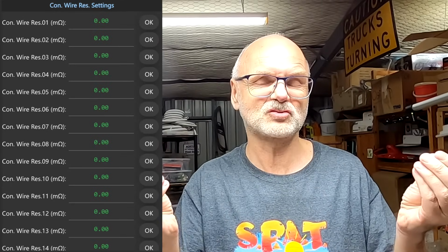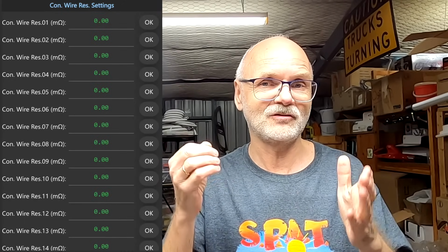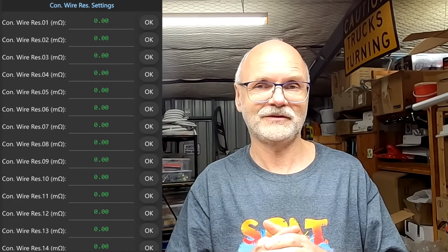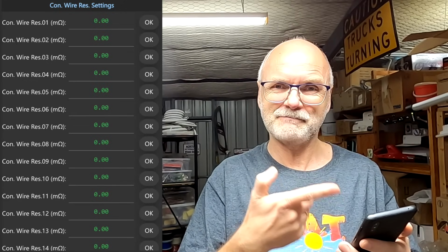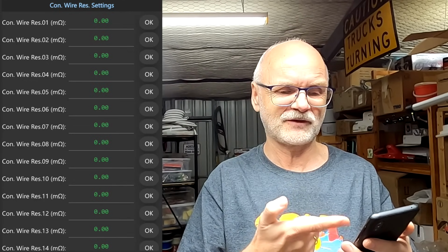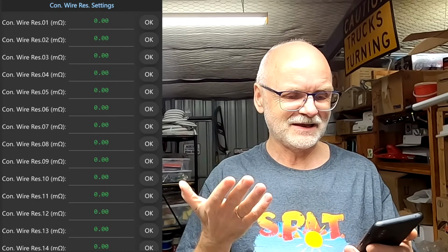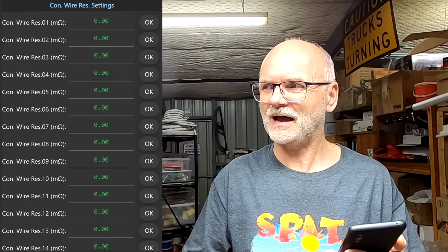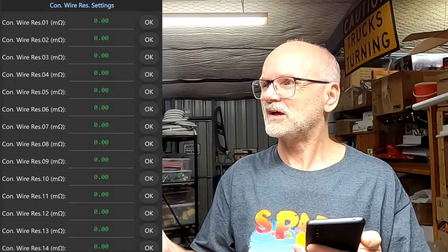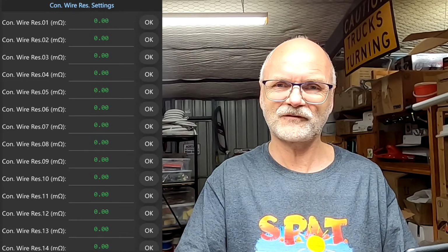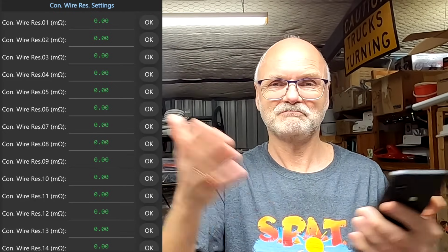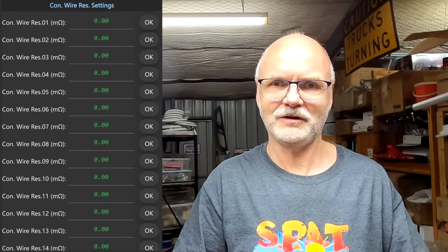There will be a voltage drop on these tiny cables, especially here with the JK-BMS, and you're pulling 2 amps from the batteries. So I'm not sure if this is a useful function here to actually measure and calibrate your balance cables for some reason. There might be applications, setups, scenarios. Leave your comments down below if you use this function here for whatever. Share what you know. Let us all be part of your experience.